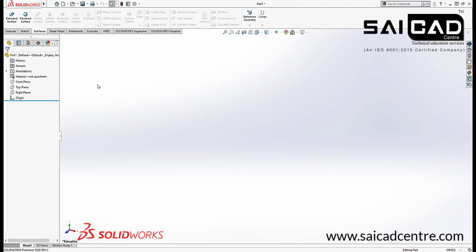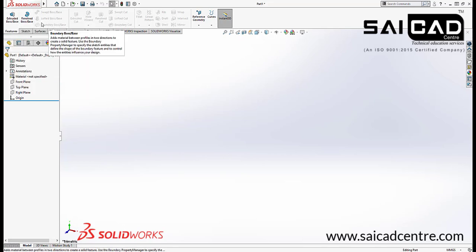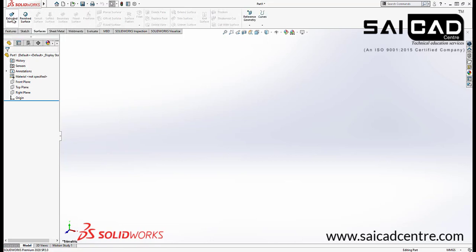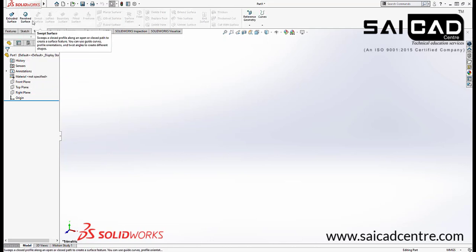So now, first of all, we have the features here. In the features you can see we have tools like extrude, revolve, sweep, loft and boundary, and you will get these tools also in the surface tab: extrude, revolve, sweep, loft, boundary. All the commands are similar, we just have to choose the command according to the need. If you want to create a solid, choose from here. If you want to create a surface, choose from here. You can see we are in surface and every command has the prefix Surface attached here.